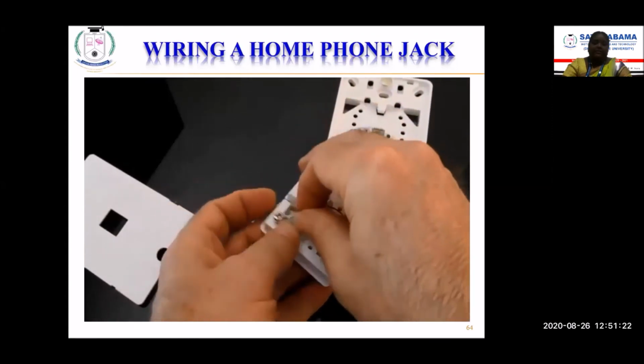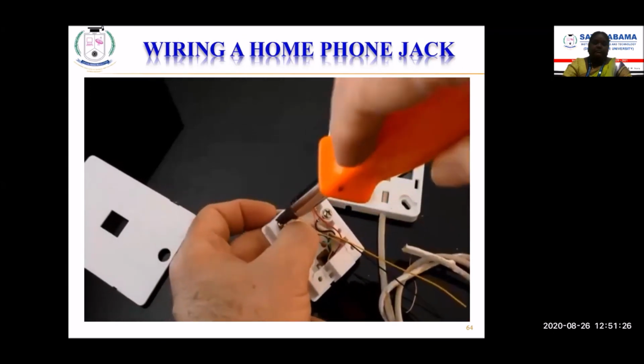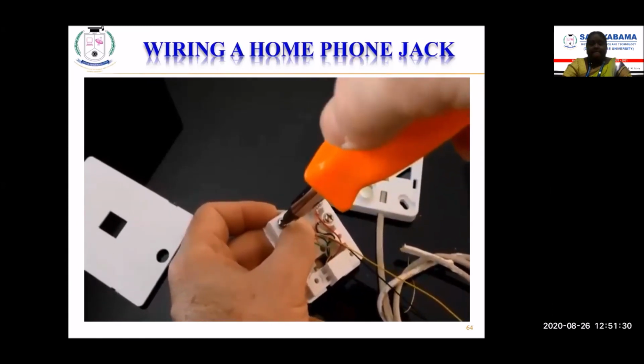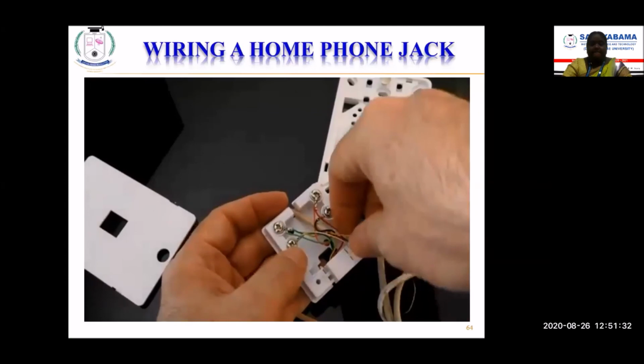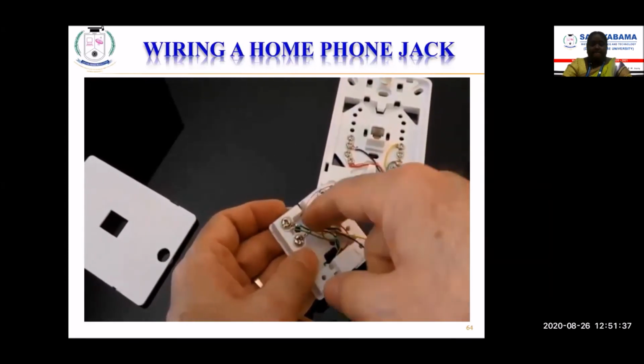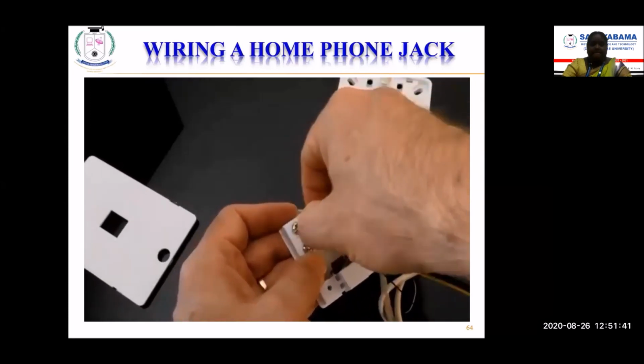That is for the green. And you don't have to wail on these. I'm sorry, you don't have to really cinch down on these screws real hard. You know, just maybe 2 or 3 pounds of torque is fine. All we're trying to do is just get the copper to be pressed up against that screw, and there's like a little metal fork in there that connects to the green wire inside the jacket.